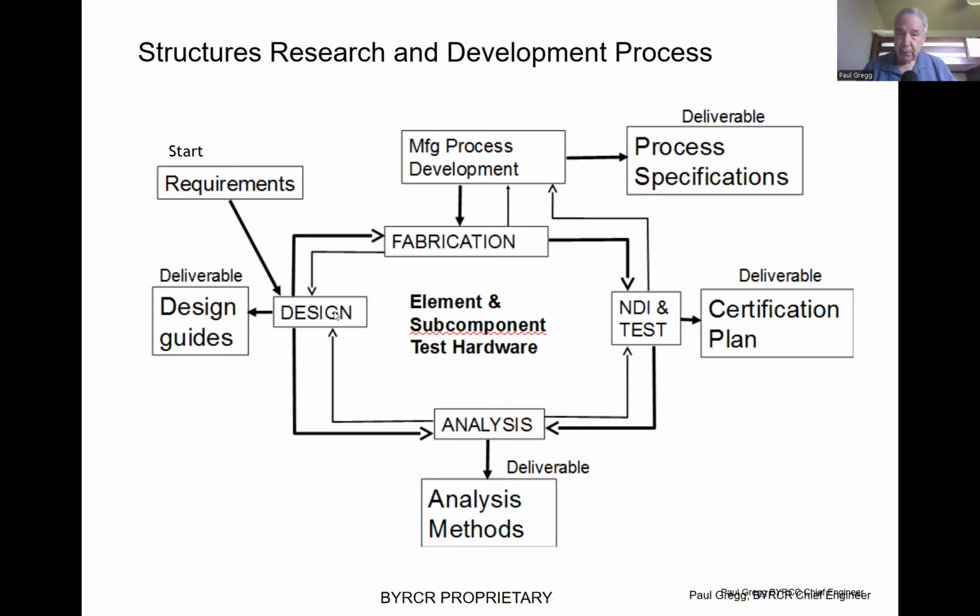So what this does for you, you design and go to analysis back and forth a bit. Then you start fabricating things, and you don't have to fabricate the whole thing or a subcomponent, generally just an element level test. And then you fabricate it. And then you do NDI, non-destructive inspection and testing.